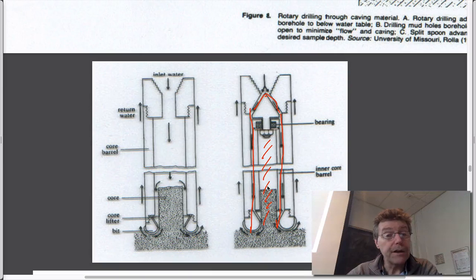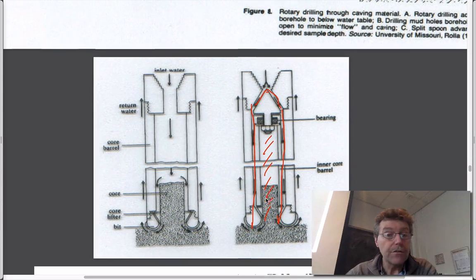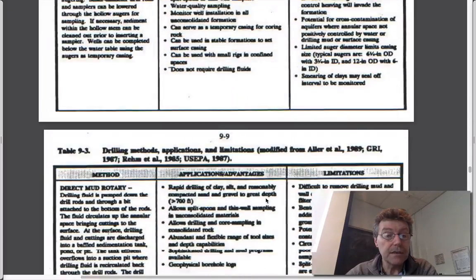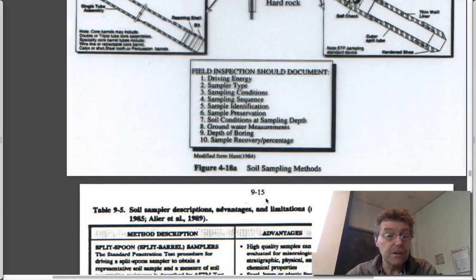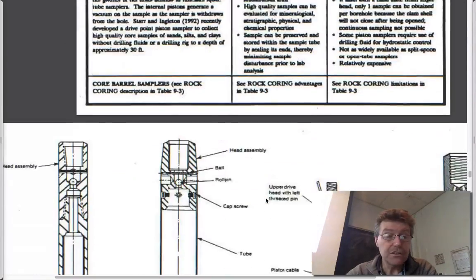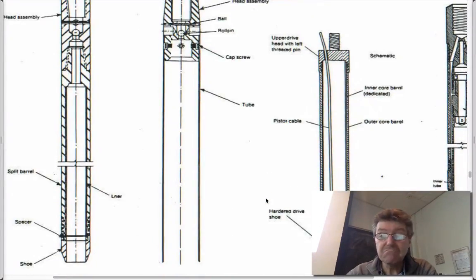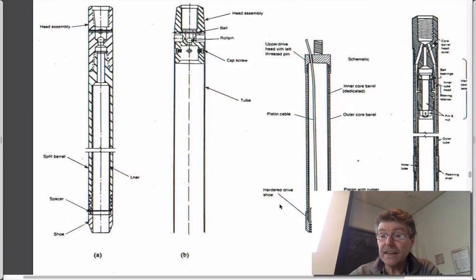And if you're really worried about that, like some microbiologists might be when they're doing drilling for science, then you might flush it with nitrogen or some inert gas rather than actually water, which might contaminate it. So that's the guts of the sampling tools that you might use. I think we talked a little bit about what those tools are. This is only reiterating exactly what those things are again. This is a multi-tube core barrel by the looks of it, where the whole interior core barrel rotates.